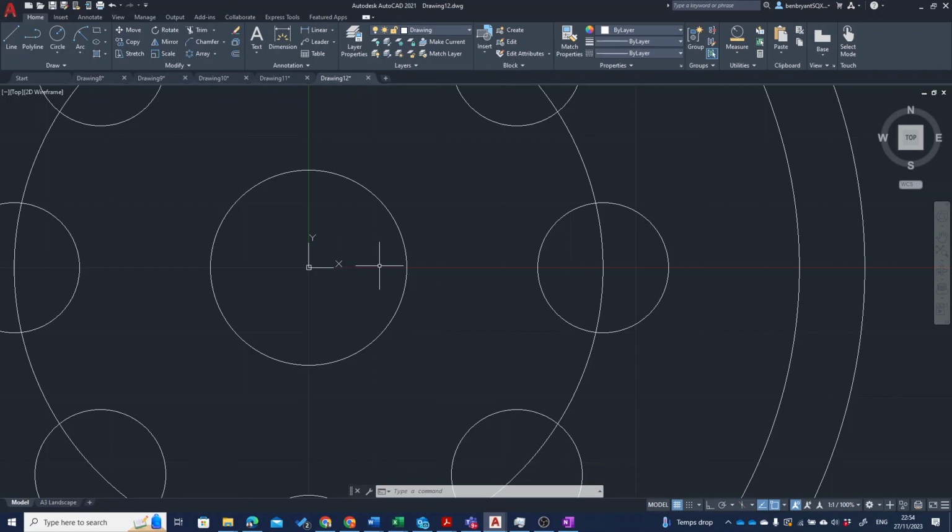Now I've got to put a bit of construction elements in. So what I'm going to do is change my drawing layer to construction. I'm going to put an Xline in on 0, 0. So I'm going to lock this to the X, offset of 5 to make the 10mm gap. That's not locked onto.